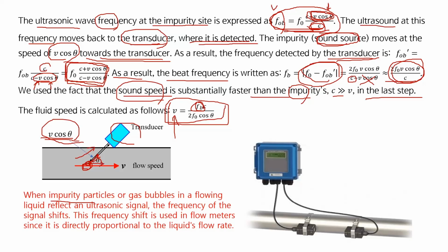When impurity particles or gas bubbles in the flowing fluid reflect an ultrasonic signal, the frequency of the signal shifts. Okay.